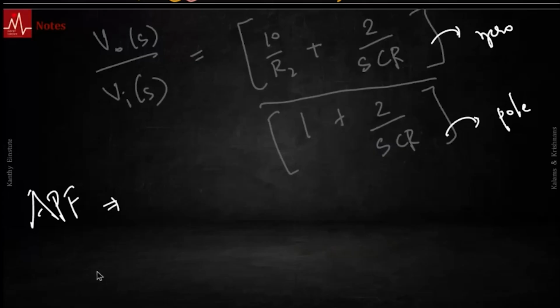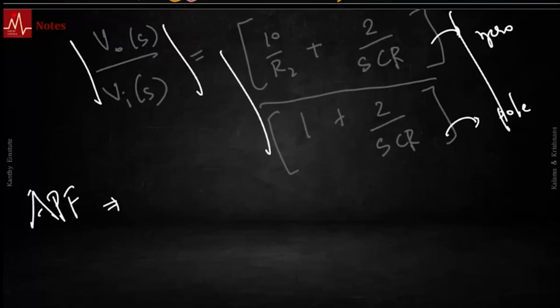Okay. Why is that the case? Wherever there are roots and poles, the Bode plot will change direction. So there will be a non-zero gain, right? No change in direction. If they are at the same point, their effects will cancel each other. Or even if you just do this all pass, let's say the magnitude is 1. There is no frequency preference. All frequencies are one and the same. All S values are one and the same.